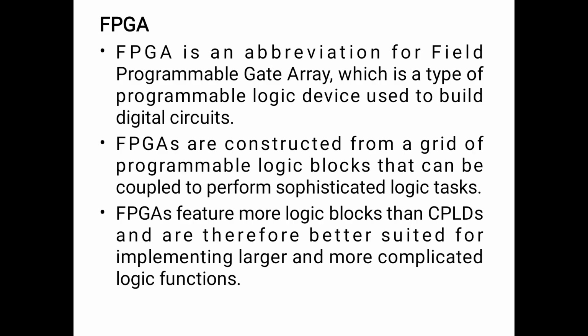FPGA is an abbreviation for Field Programmable Gate Array, which is a type of programmable logic device used to build digital circuits. These are constructed from a grid of programmable logic blocks that can be coupled to perform sophisticated logic tasks. It features more logic blocks than the CPLDs and are therefore better suited for implementing more complicated and larger logic